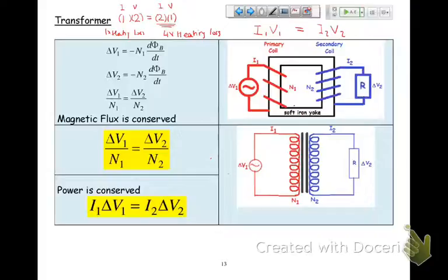So I actually get myself some laminated soft iron, and I basically make it, because what this will do is entrain the magnetic flux lines, so that every flux line coming out of here goes in through there. So it makes it like they're magnetically really well coupled. The trade-off is it becomes quite heavy. So if you pick up a power supply, it will have a transformer inside, and that power supply weighs a lot. It's because of the metalwork in the transformers. Okay.